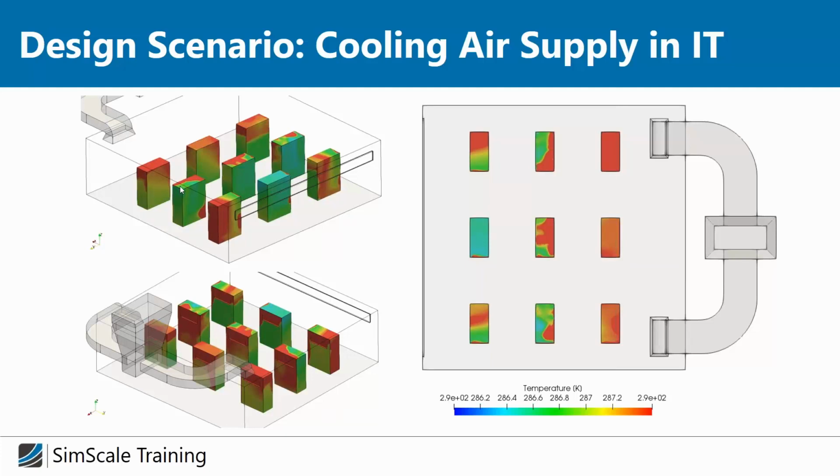And as you know, when designing such a cooling system, I'm interested in the end in the max temperature. So whenever the temperature is too high at just one rack, I need to increase the cooling rate until everywhere the temperature is below the critical temperature. Therefore this non-uniform distribution of heat is really a problem, and this design is not optimal.